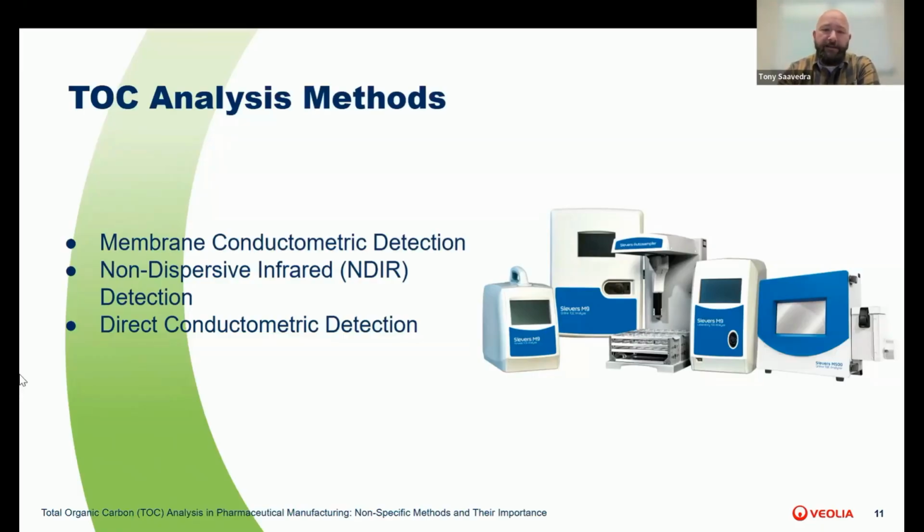In short, TOC is calculated from the difference between the total and inorganic carbon within a sample. Organic carbon is oxidized by analytical tools, then converted to carbon dioxide, or CO2. And then after oxidation, the resulting CO2 can be detected by the tools. Different analysis methods have their strengths and suitabilities depending on specific applications.